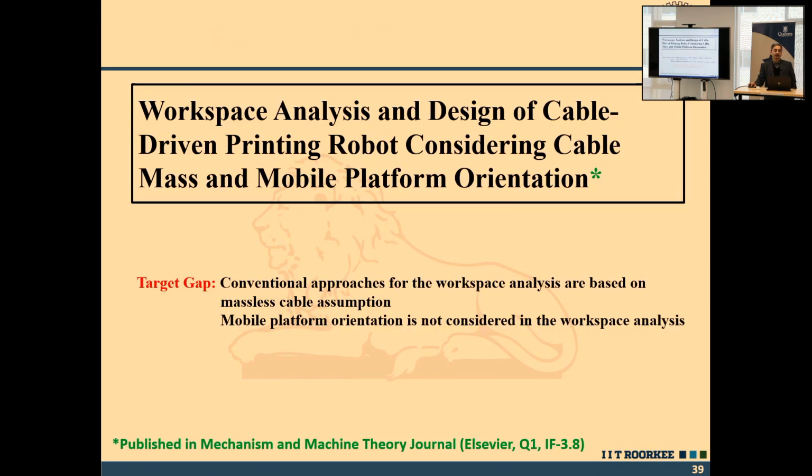Next, we did the workspace analysis, because workspace is really one of the challenges here. Initially you get a larger width, but as the height increases the width keeps on reducing. So, we carried out workspace analysis and design, considering cable mass and mobile platform orientation, and we found that there is a substantial improvement in the workspace area when we also consider the mobile platform orientation.